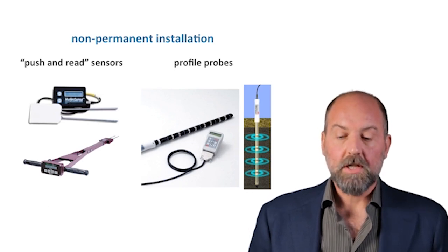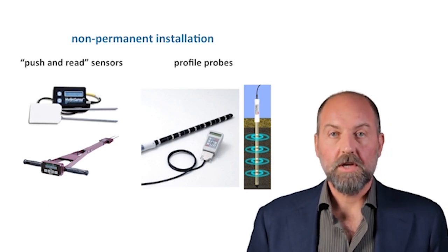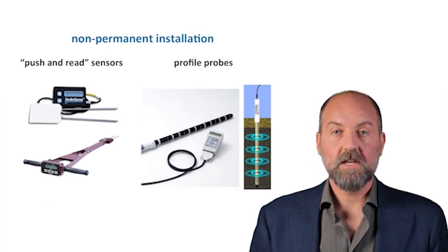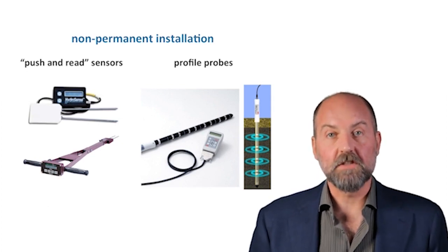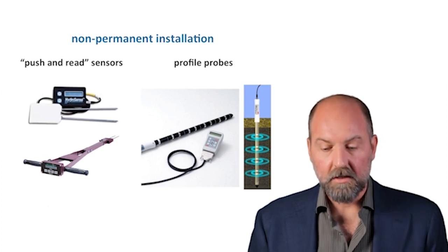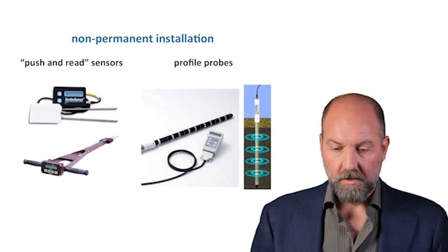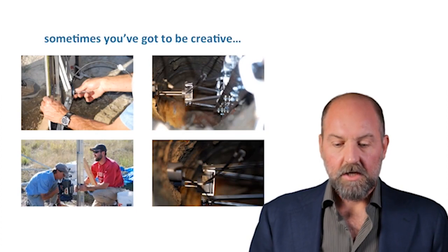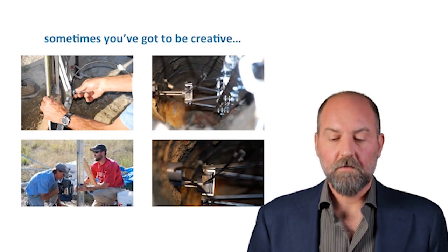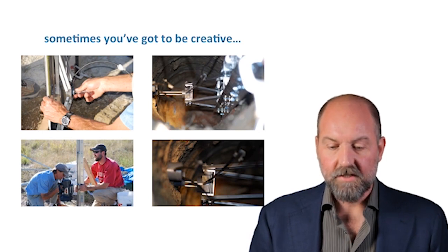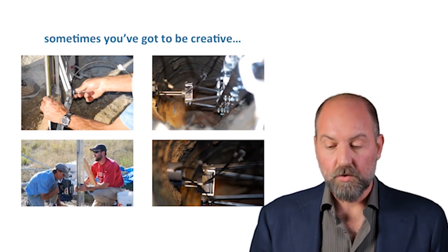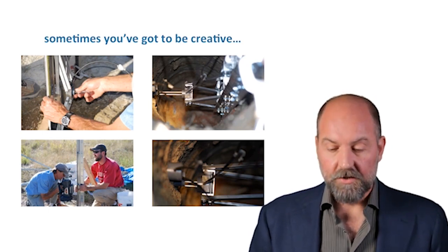gap between electrodes and soil. What is to be avoided at all costs is the formation of air gaps. In other words, we need a very firm contact between the metal electrodes and the soil. And here I have some image of a contraption that I have developed in the past for installing probes up to 2 meters underground.